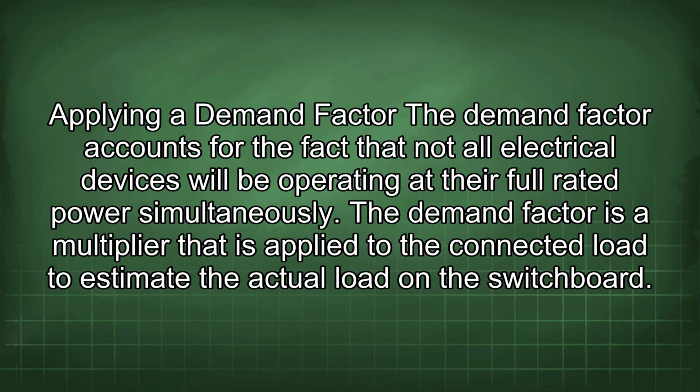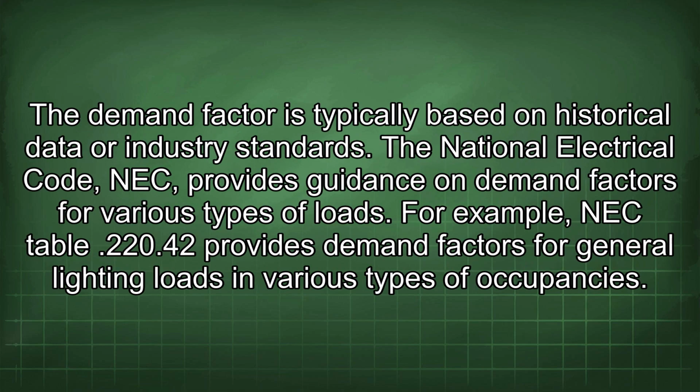Applying a demand factor. The demand factor accounts for the fact that not all electrical devices will be operating at their full rated power simultaneously. The demand factor is a multiplier that is applied to the connected load to estimate the actual load on the switchboard. The demand factor is typically based on historical data or industry standards.